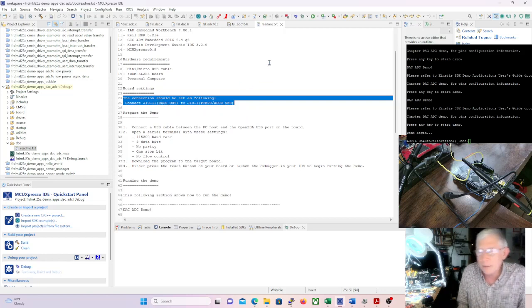So you're going to connect the output of the DAC to the input of the ADC, and then it's going to allow you to pick from about 4 different values. It's going to output that value for the DAC. You're going to read it in the ADC, and the ADC is going to print its value and convert it to the voltage, and then you're going to see how accurate it is, what the precision is.